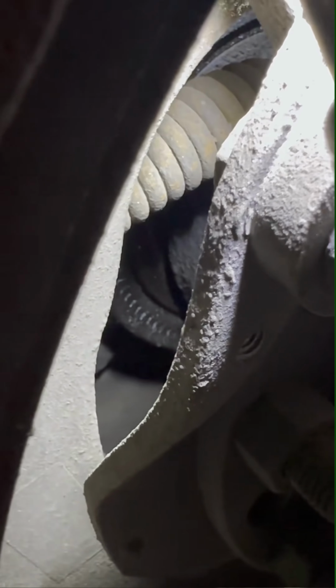Starting to leak also. And anytime you have both wheel seals that are leaking, or anytime in general, it's a good practice to check the breather and the hose to make sure it's not plugged up. This breather was okay. It was breathing, it had a pulse, and the hose was not restricted. It flowed within spec, 50 breaths per minute.